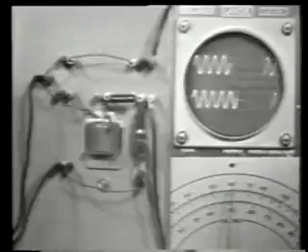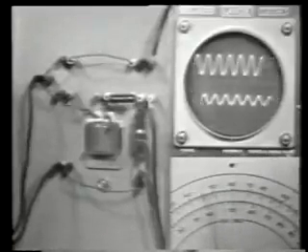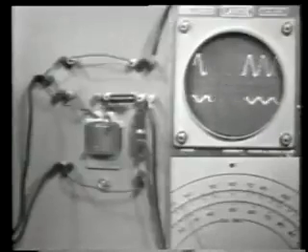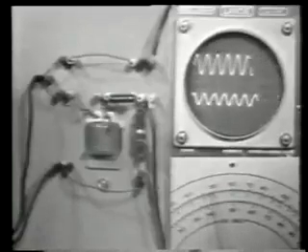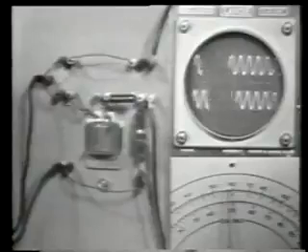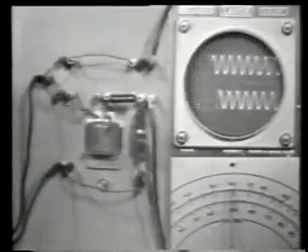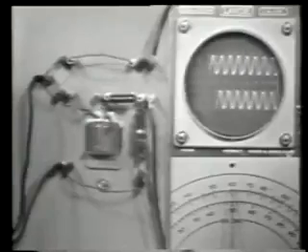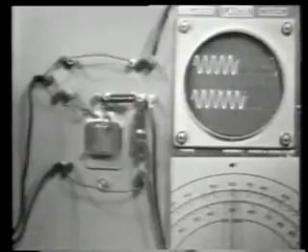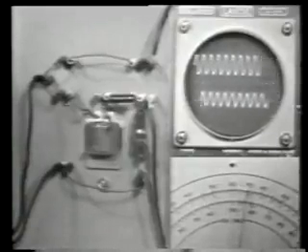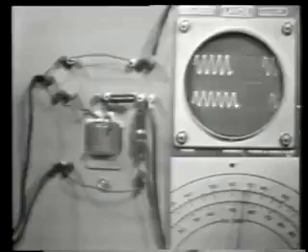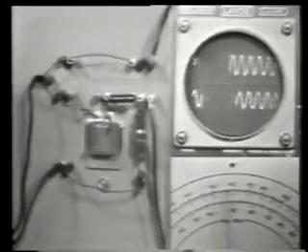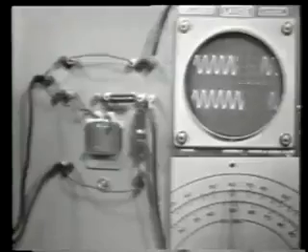Now, at frequencies below 500 hertz, the output drops to minimum, as you can see. Now, as I increase the generator frequency, you'll note the output start to rise until at about 600 hertz, the output is maximum. As a matter of fact, it's about the same as our input frequency at this point. Now, further increase in frequency causes the output voltage to decrease again. So we're passing just this small band of frequencies between 500 and 700 hertz.